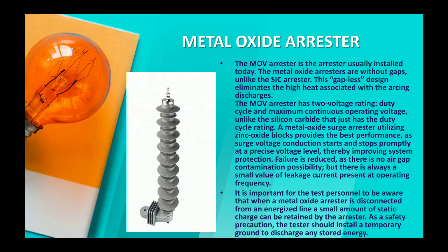If there is any stored energy or any static charge present, it must be discharged through the earth. Otherwise, the person who is operating the metal oxide arrestor may be shocked due to this static charge which is retained by the arrestor.